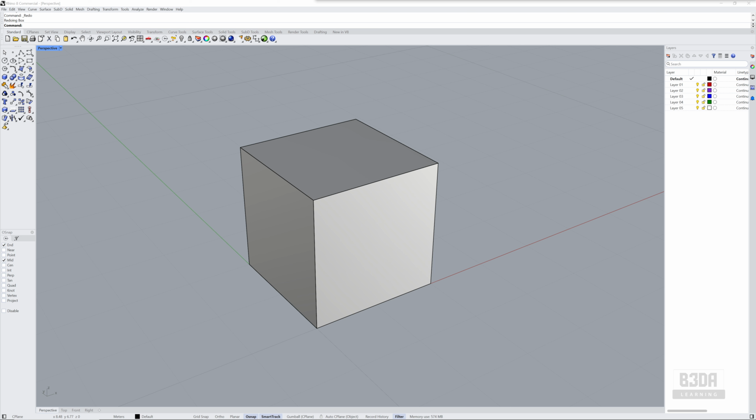If you are starting with Rhino, let me show you how to work with both 2D and 3D rotations. I have a simple object here, and we can use it as an example. If you want to rotate this object, you can choose to either use a single point as a pivot for your rotation, which will be a 2D rotation, or an axis, which can be any combination of points or lines or references on your 3D object.